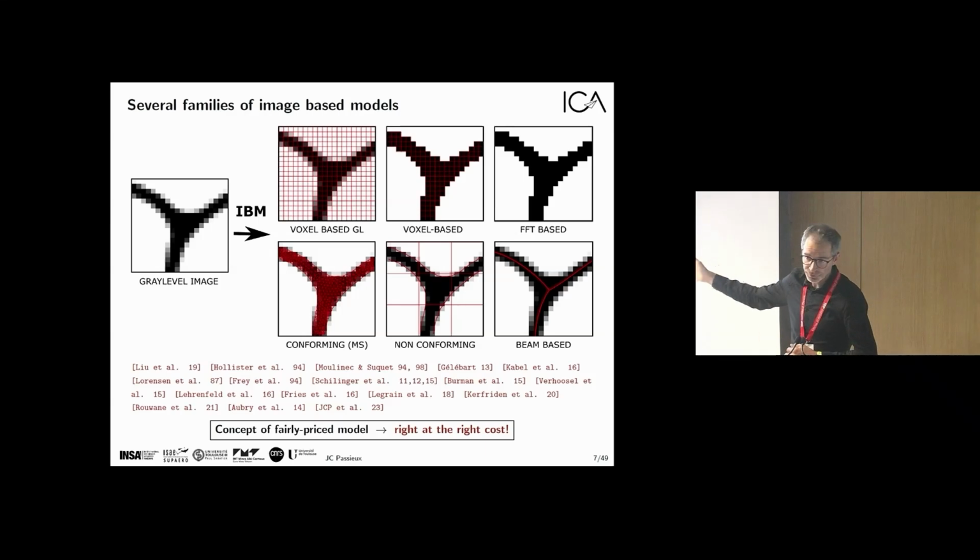There are also conforming methods like marching cubes, marching squares, that aim at building a FE mesh that fits the boundary of the domain. There is also a family called unfitted boundary method, also called a fictitious domain method or finite cell method or cut-FEM.